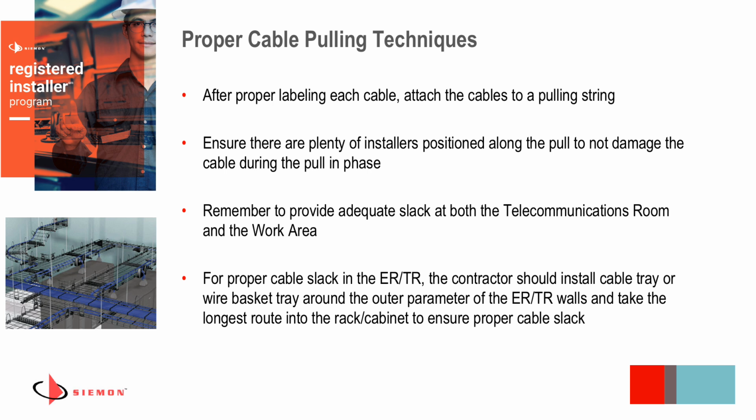Also, you want to make sure there's more than just one person back in the telecommunications room, but you want to have people along the way to help distribute that pulling force and inspecting. If you have any cable turns along the pathway, you want to have people helping to manage that and ensuring the cable's not getting damaged as it's being installed.